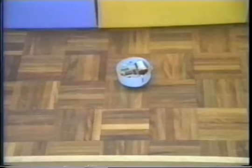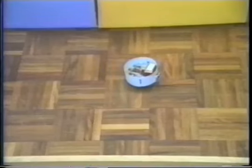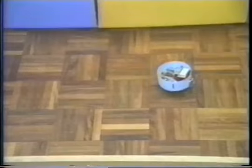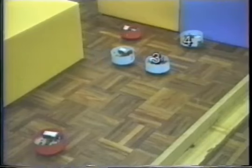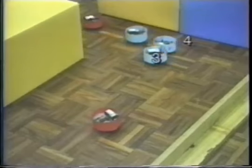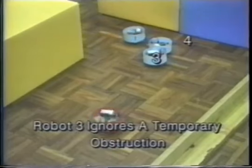When heat is detected, the robot turns to follow the trail. Because the robot's pyroelectric sensor is only sensitive to heat changes, the robot follows the trail by repeatedly moving forward and then rotating to detect the edge of the trail. If a temporary obstruction blocks the trail, the robot is programmed to wait a length of time proportional to the time it has been following the trail.